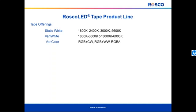And then we've got 3 ways that you can create colors or mixed colors. We've got an RGB plus cool white, an RGB plus warm white, and an RGB amber vari-color tape. All of the tape is standard in IP43 or indoor rating, but we can also provide any of these flavors in IP65 outdoor rating upon request.